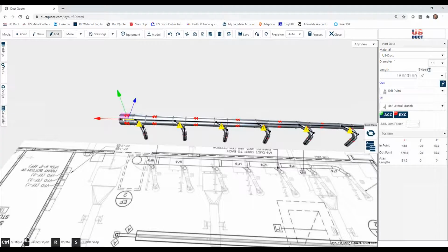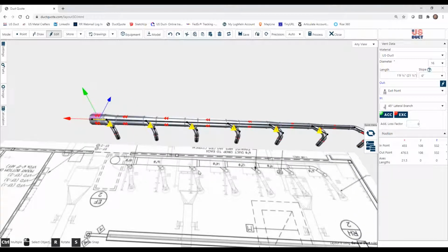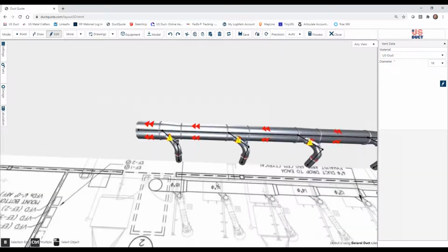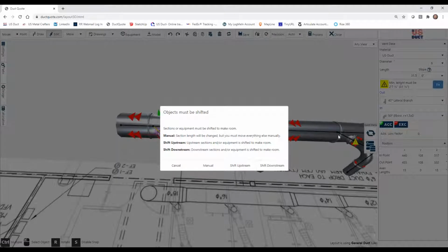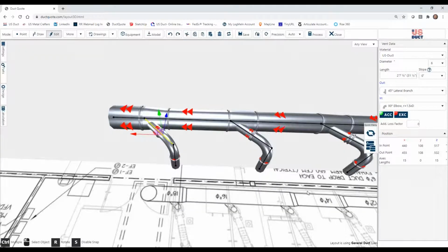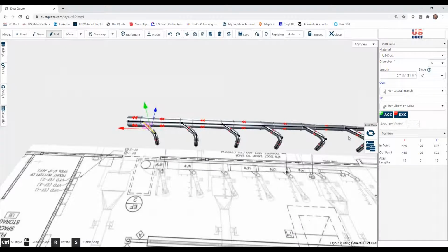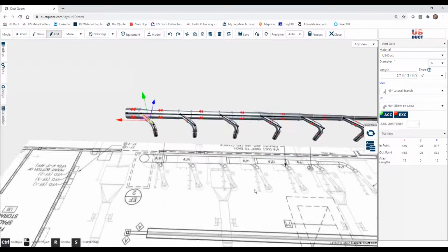And you can see that we ended up with a 16-inch, not an 18-inch as they had. But what we are going to do is fix starting here. I'm going to notice that 21 inches is how it's drawn, and it needs to be 31 inches. So I'm going to fix that downstream and watch what happens. Notice that that also fixed all of these because they got a little bit longer.